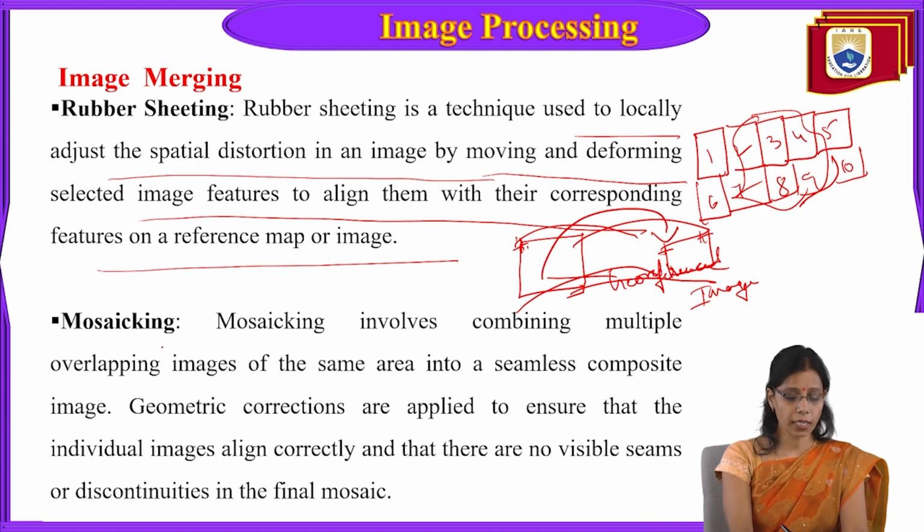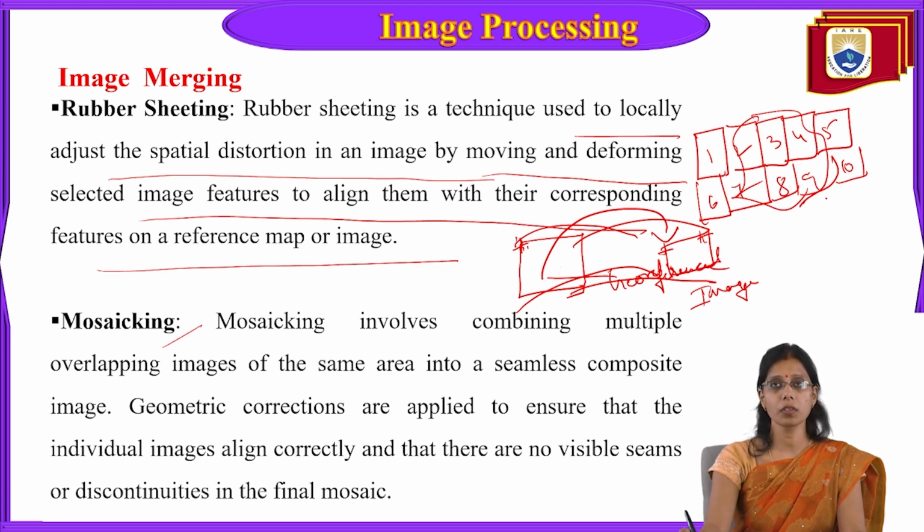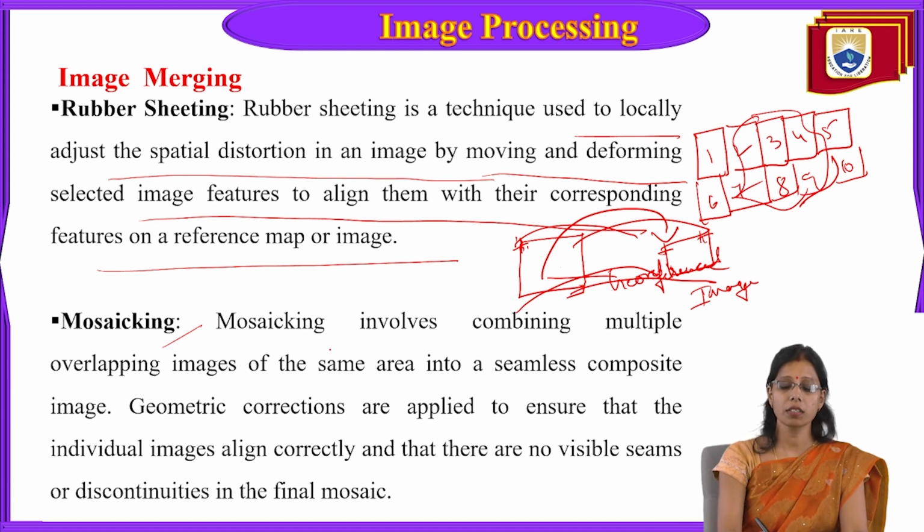Next we go with the mosaicing process. In the mosaicing process, as I said, the images come in 10 parts or 30 parts or 100 parts. So we separately georeference each of the images like this. Georeference 1, 2, 3, 4 points. Here 1, 2, 3, 4 points.